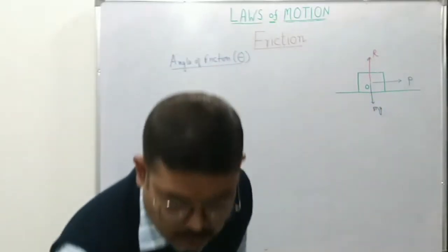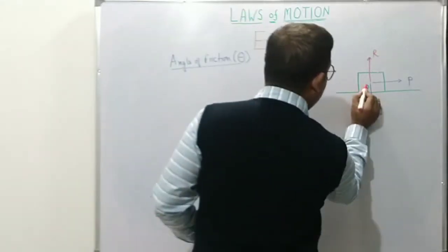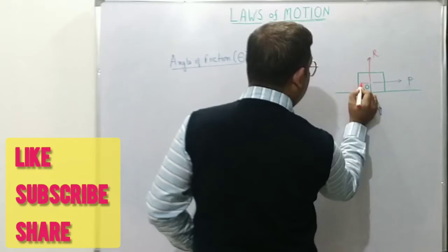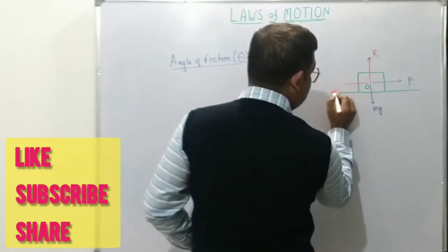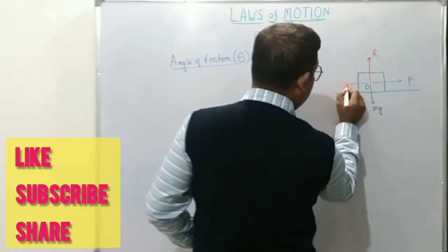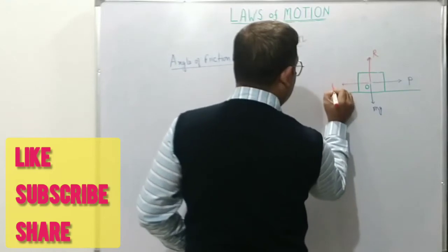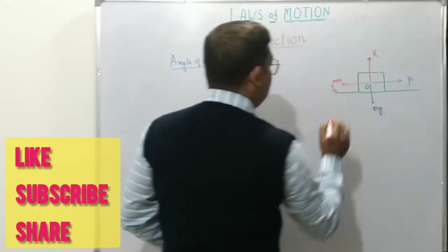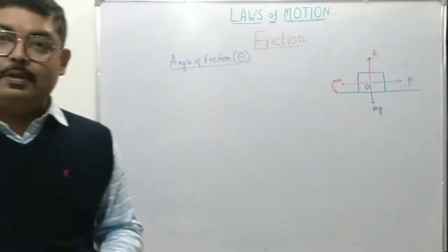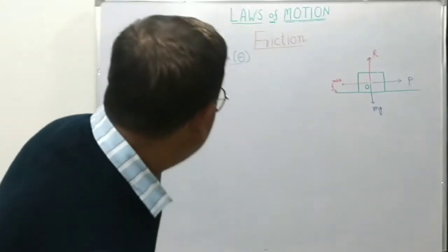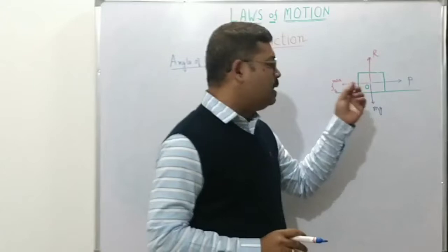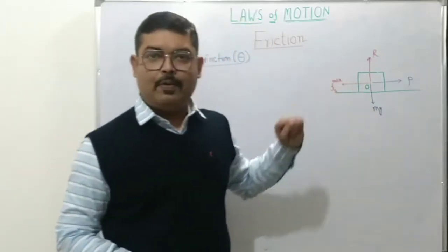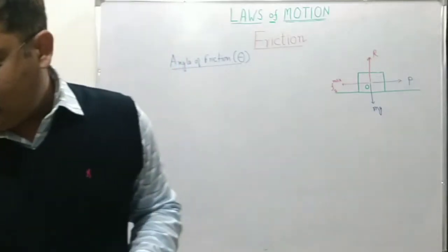friction. That opposition force will be along the tangent, but we have put it here so that it becomes easy for us to draw the diagram. And we have Fs max here, the maximum amount of static friction. The applied force is just about equal to the limiting friction, that is, the object is just about to move. Under such condition,